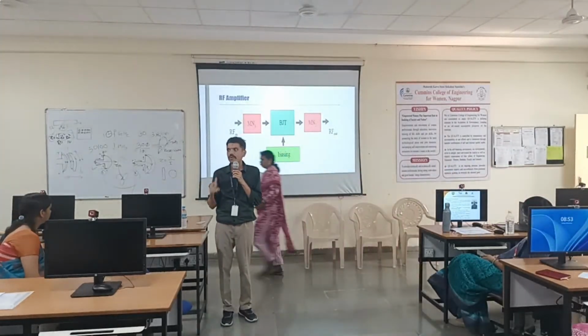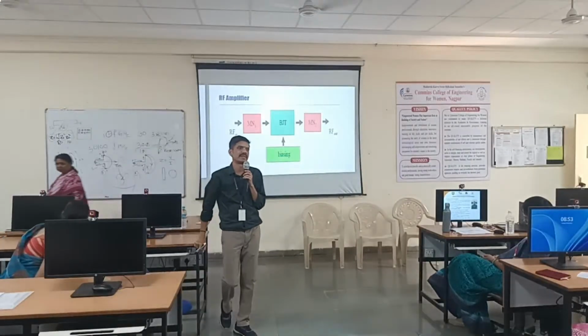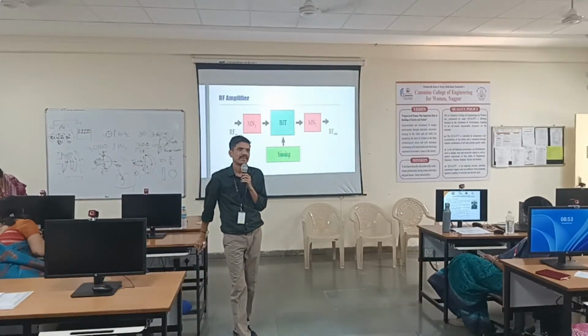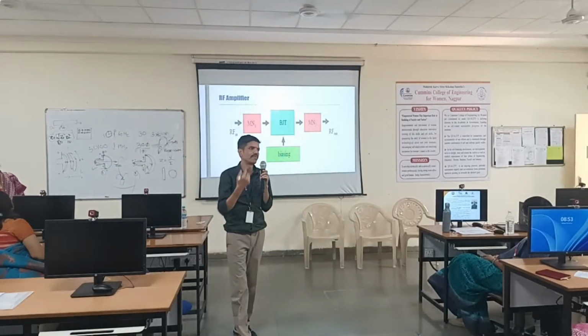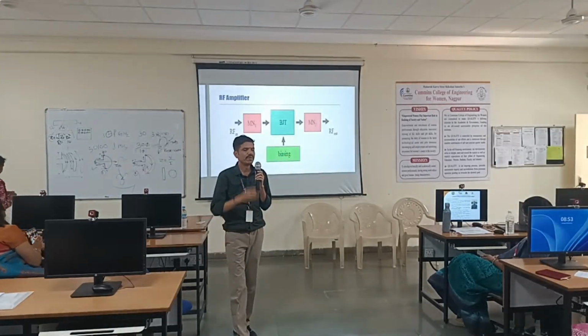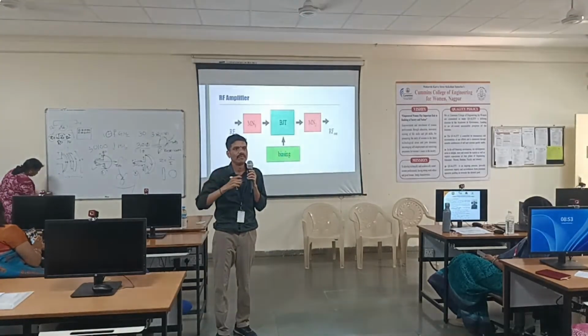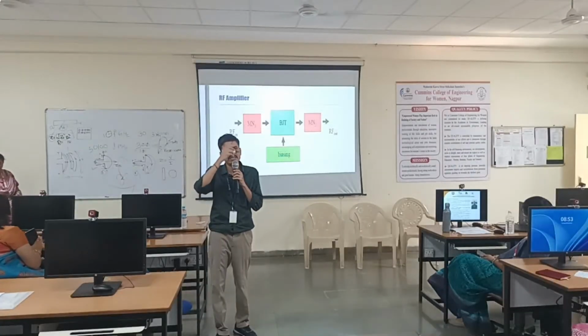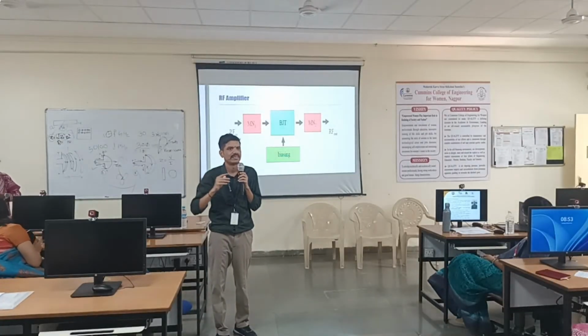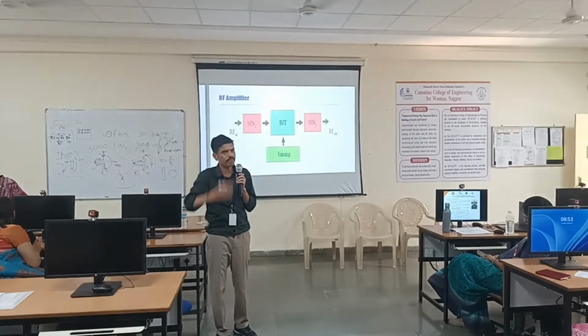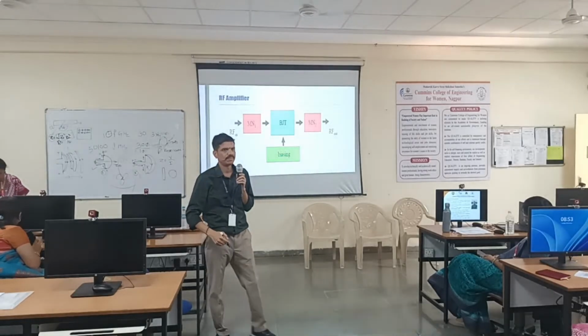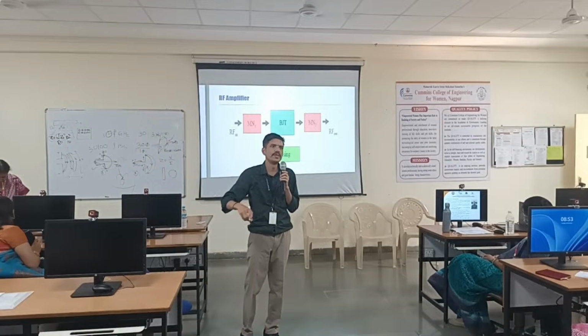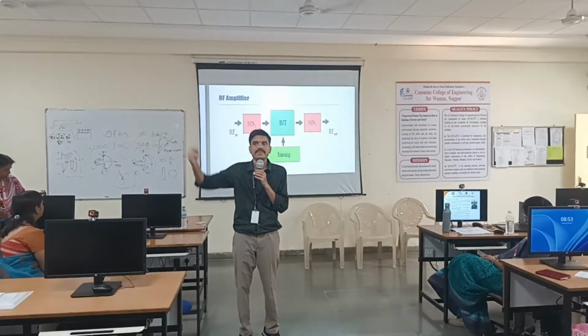Right? So what do you have to do to make it broadband? Let us pick the concept from our filter design. We have different LC filters, right? Based on orders, our response will change. To get the sharp roll off, or cut off, we increase the filter order.